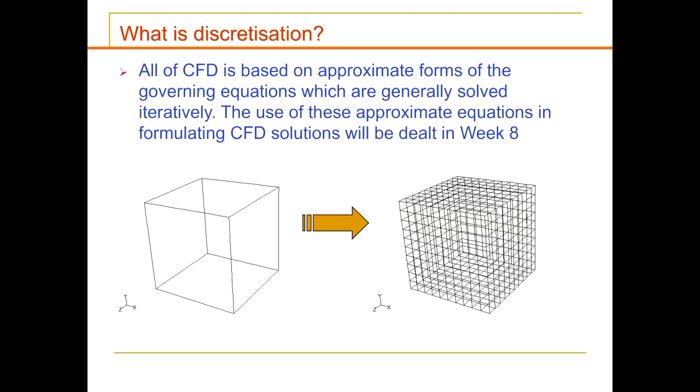Within each small element you have the algebraic equations of the conservation laws. Let's say, for example, you solve the mass, momentum, and energy for each of the elements. From each element, you march to the adjacent element and consider it, to effectively solve the flow throughout this room. You understand that?